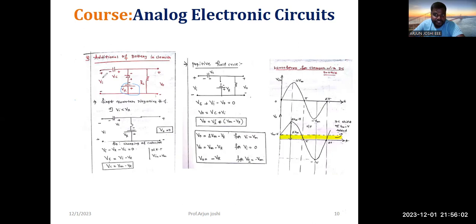But what is the first step? Here we need to make the diode on. So that's why minus plus. In that case, our diode will act as a closed switch. Whenever the diode acts as a closed switch, V naught is equal to 0. Obviously, we know. Please apply the KVL: plus Vi plus minus Vr minus Vc is equal to 0. Vc is equal to Vi minus Vr. Vc is equal to, we know the equation, Vi minus Vm. You need to substitute Vi is equal to Vm.